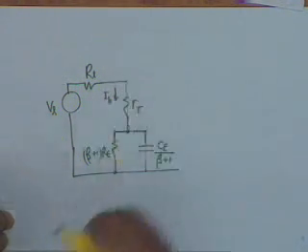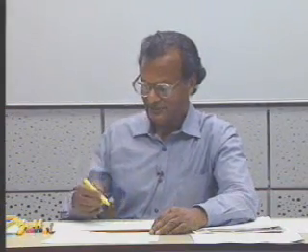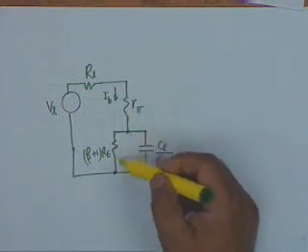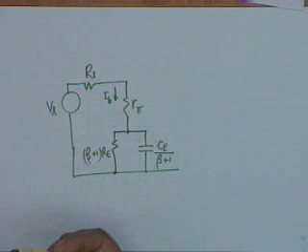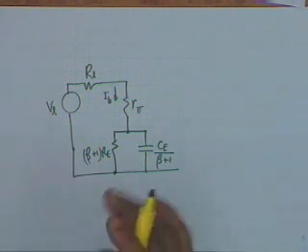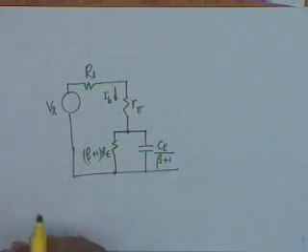You see, the advantage is that I have decoupled the output circuit. Now, what will be the effective output circuit? Just let us look at that. Is this point clear? That I have allowed a current IB to flow through this. So, what I have done is I have jacked up the resistance by beta plus 1, I have reduced the capacitance by beta plus 1, and this is an exact equivalence. I have made no approximation.